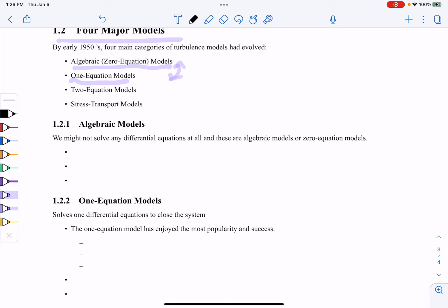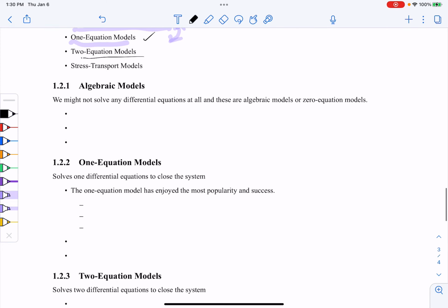So usually if you're running CFD codes today, like in industry, if I was asked to find the flow over an aircraft, I would probably choose a 1-equation model because 2-equation models are a little more expensive, and I only have so much money for computers. If I'm looking for a jet flow or some more component flow, I generally choose 2-equation models, because they're very robust, they're complete models and less computationally expensive.